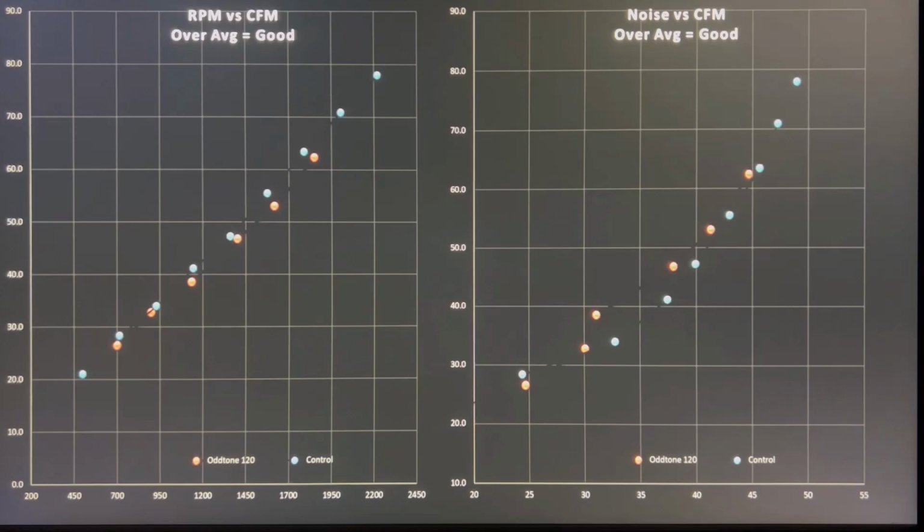So it hides a lot of the inconsistencies in a fan, because you're placing it up against the tube. If a fan tends to shoot air off to the sides, the walls of the chamber that it's in are going to still direct the air down the tube. So it's going to hide the fact that it's shooting the air off to the sides and make a fan look like it's performing better than it is in a case airflow application.